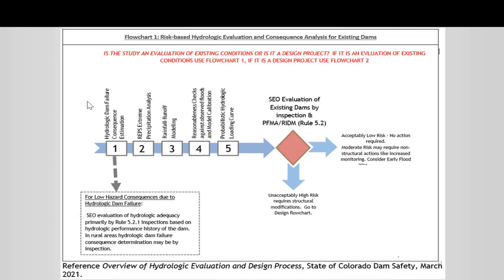Most of our dams are earth dams. We're generally talking about overtopping dam failure. But we have other types of dams. There may be different critical hydrologic PFMs, but we do the dam breach analysis for that PFM and estimate life loss consequences. And that's by our guidelines for hydrologic hazard analysis, and we use Reclamation's RCEM, Reclamation Consequence Estimation Method, to estimate life loss consequences.